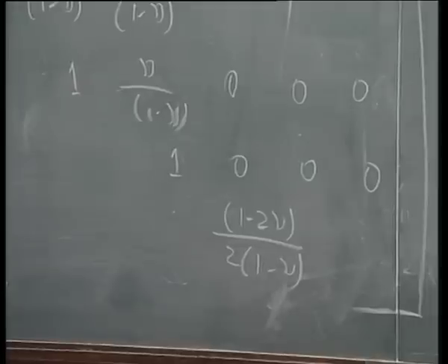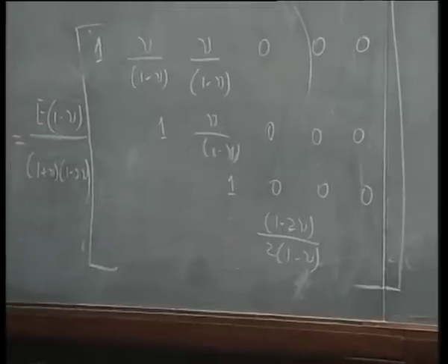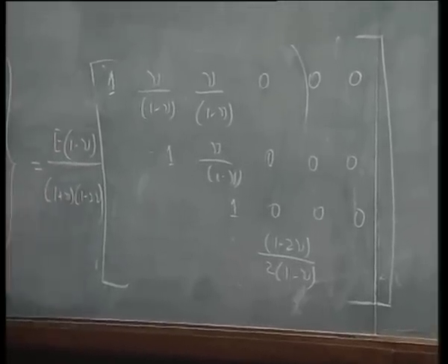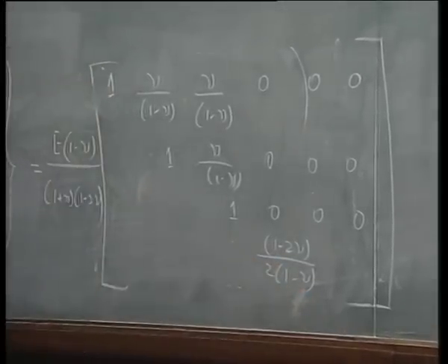So, do you get, say, now multiply this and that, E divided by 2 into (1 plus nu), which is G. So, you are correct. So, you will fill this up for the next 2 columns.